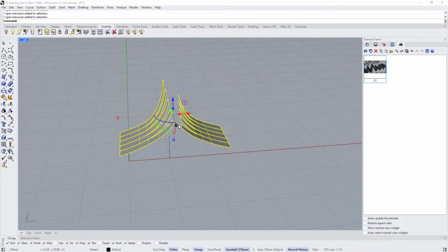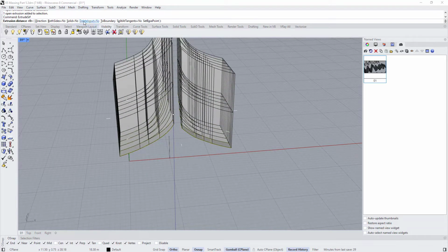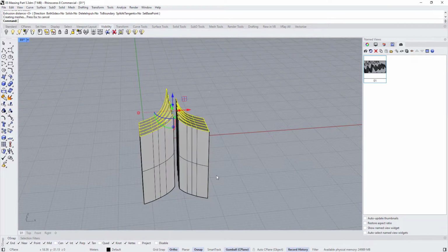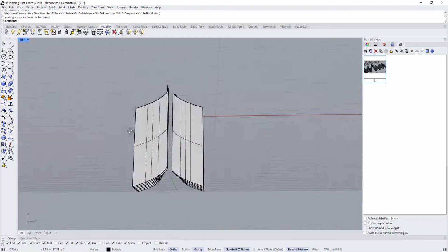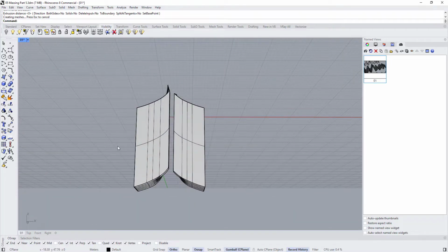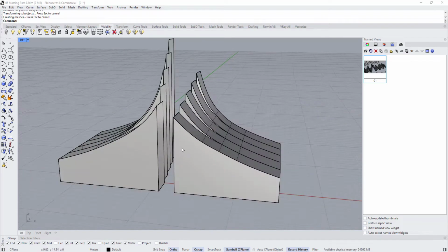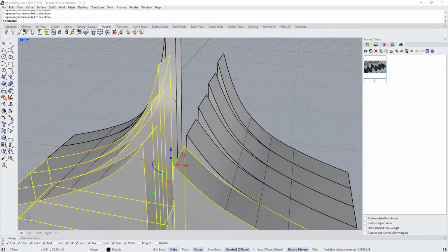And now I'm going to use the extrude command. I'm not going to use a gumball, let's just use extrude surface and choose delete input to no. Make sure delete input is set to no, and extrude them like this. Then we can hold Control Shift to select these faces and type set point to Z. It broke the history of the extrude command, it's fine anyway.